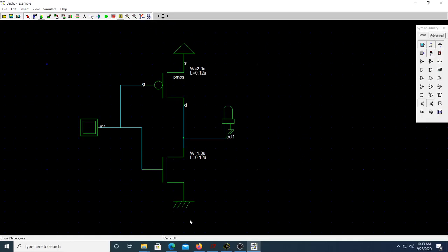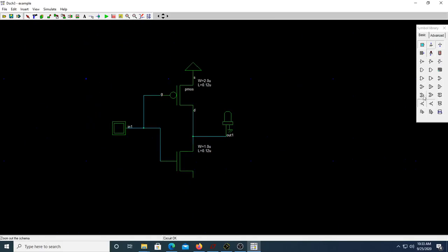So let us do one NAND gate. For that, okay, let me have, you can delete this. I can delete this. Okay, let me keep it there as it is. And let me have one more NMOS. Where is NMOS? This is NMOS. Let me drag it and place it here. Let me minimize this. Okay. Let me put one NMOS. Let me put one PMOS.